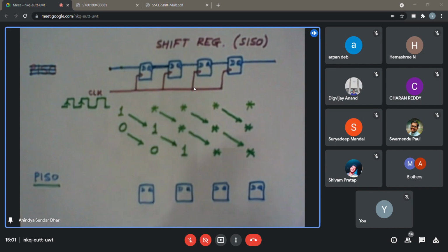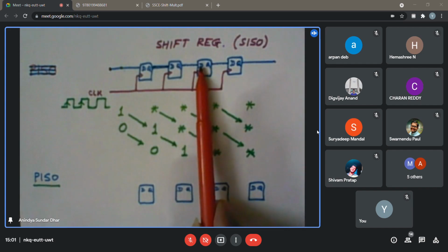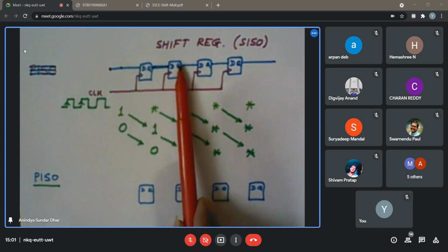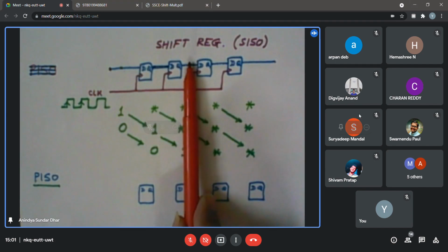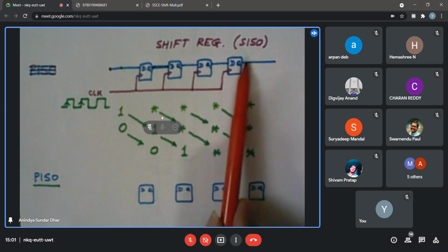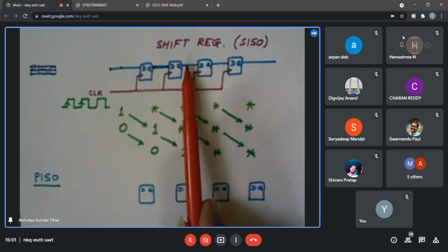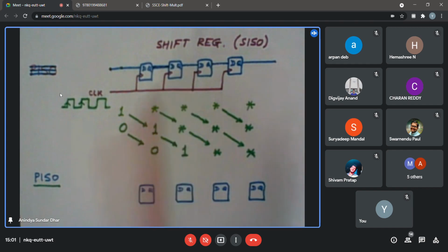So certainly, I think there is a choice, as we are saying, for each of these flip-flops, that either it takes the output from its neighbor, which is basically facilitating the shifting process, or it can have a parallel load. So maybe I can identify two distinct operations. One is the parallel load operation, and the other is the shift or serial output mechanism. So shift or load, there are two distinct operations. Maybe I can give the user a single control line saying that if this is high, then do the load. If this is low, then do the shifting operation. And accordingly, as you have suggested, use some sort of combinatorial logic which will steer the appropriate signal into the D input.